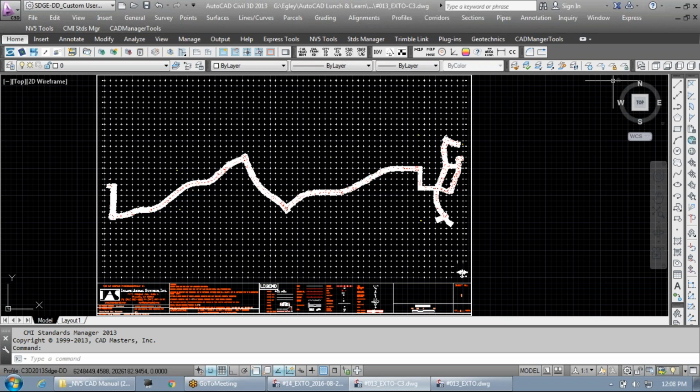We talked a little bit about knowing your file size, what size file you're anticipating. It's always good to have your XREF window open so you can see the file size. Make sure that it makes sense. Do a sanity check on your file size. If you start seeing it get bloated, something might be happening to your file. Maybe it's a good time to purge. Maybe it's a good time to audit.